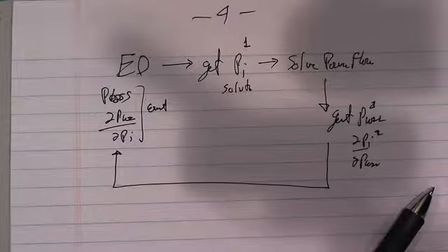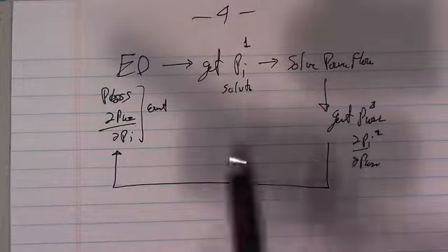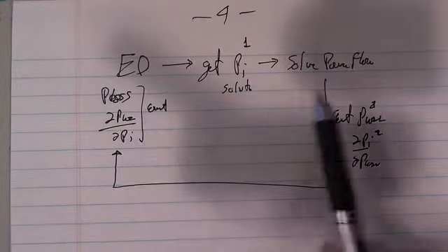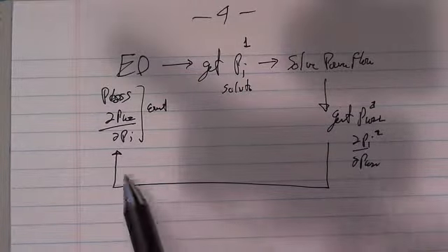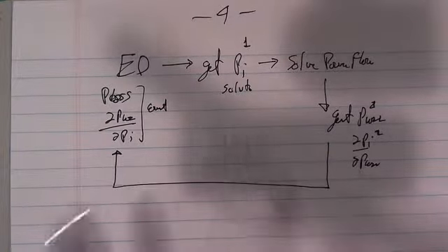The process will converge. This is called a relaxation process. We're going to show how to do unit commitment with something called Lagrange relaxation. Relaxation is just we know that this is a variable, but we're going to just hold it constant while we do this other thing, and we'll come back. And it's used all the time, okay? So these start out to be constants. We get new values, and we feed the new values over, and we solve it again.